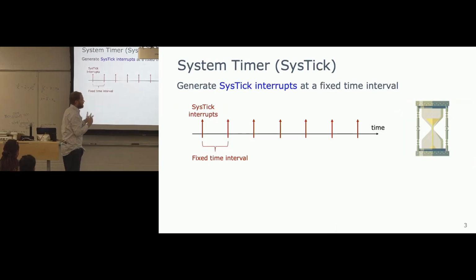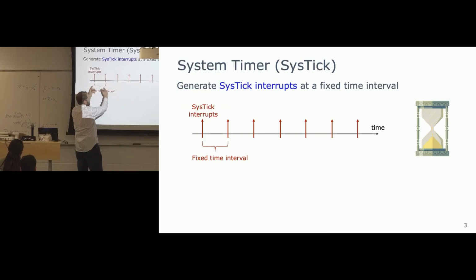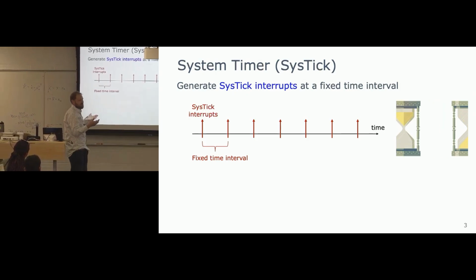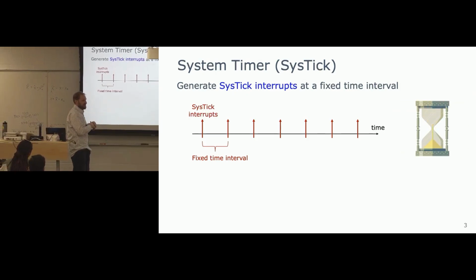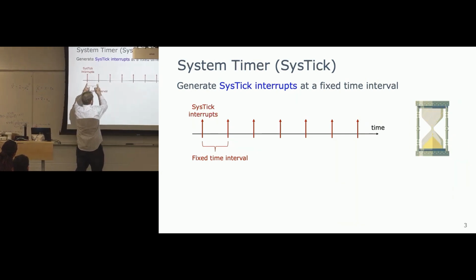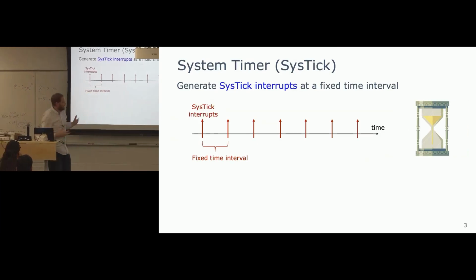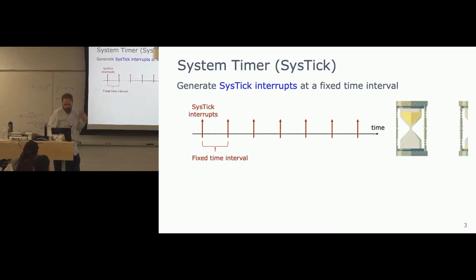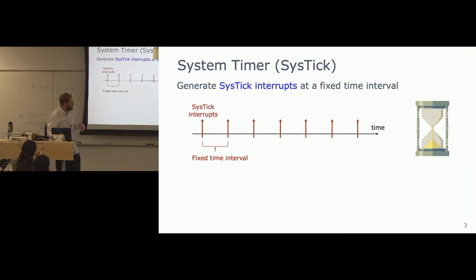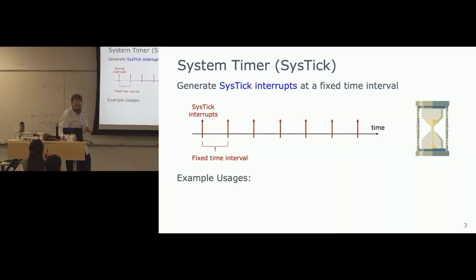There's a difference between hard timing constraints and soft timing constraints. Hard timing constraints would say if you don't get it done, your system fails, right? The plane falls out of the sky. Soft timing constraints would be like, okay, you failed to meet that, but the user really didn't notice because they're just touching the in-seat entertainment system. It's not mission critical. But anyways, the goal is to try and get your tasks to end within that period of time, and then you're just going to switch through tasks. You might have tasks that have different priorities, and you want to make sure that those go through. You have a queue, just like you have with your interrupts, and you're making sure that those get done first.